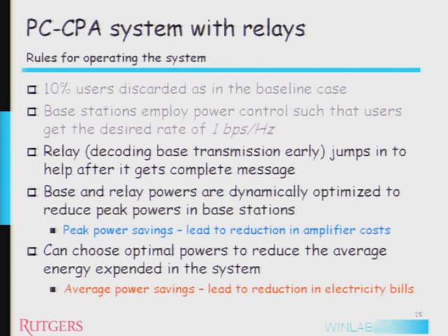So the relay is not actually going to store and forward, and it's also not going to transfer the same message as the base station. It's actually a code. You can think of a code which I can build at the base station and the relay. Let's say the relay has a very good channel to the base station. It can decode the code word in a lesser number of symbols, and then it knows exactly what the message is. After that, it's going to transmit another code word.